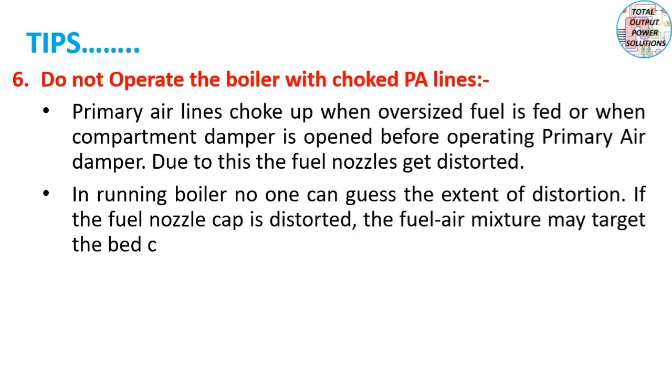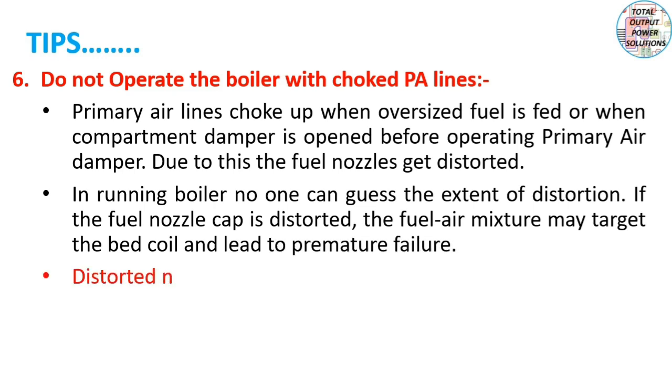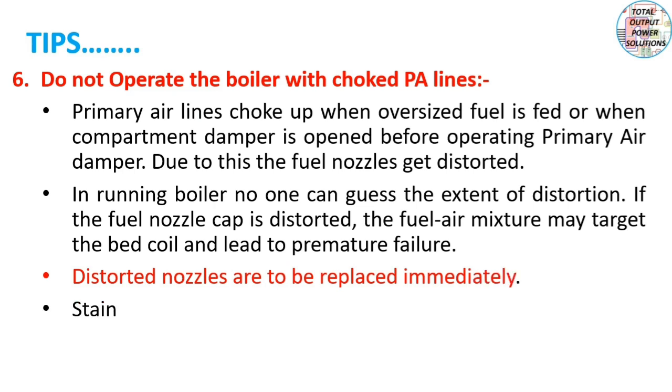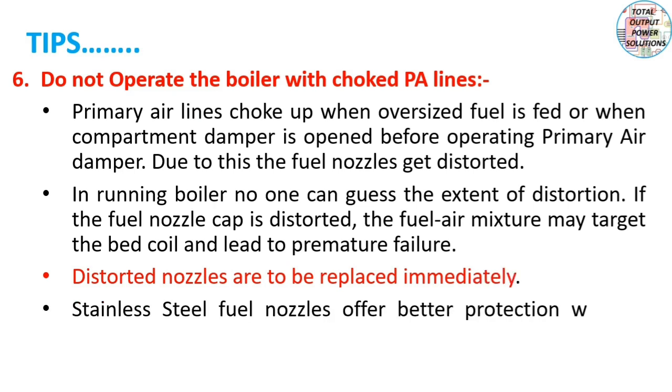If the fuel nozzle cap is distorted, the fuel-air mixture may target the bed coil and lead to premature failure. Distorted nozzles are to be replaced immediately. Stainless steel fuel nozzles offer better protection when it comes to bed coil life.